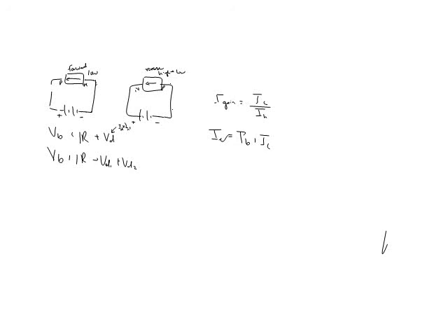Think of it as like just a plastic screen or a plastic coating, and it has these little tiny holes in it. Then they stick the wafer with the coating on top of it into a vacuum chamber and vaporize the dopants. And the vapor condenses onto the protective coating, and then they take it out and they pull the protective coating off. So everywhere there was a hole, now there's a dopant.